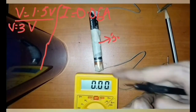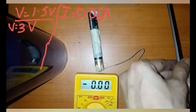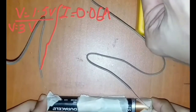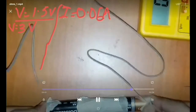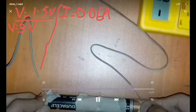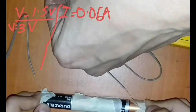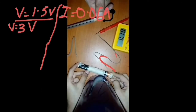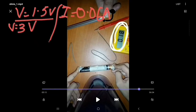That is, I am increasing the potential difference, or the voltage, and I'm just going to measure the current here, because you know that the voltage will be somewhere around 3 volt only, because it is written on the battery and no other circuits are there, so we will be getting almost 3 volt potential difference. Now what we need to do is to measure the current. In order to measure the current, as I told, we have to connect the positive of the battery to the positive or red terminal of the multimeter, and then you have to keep the black terminal on the pencil lead.